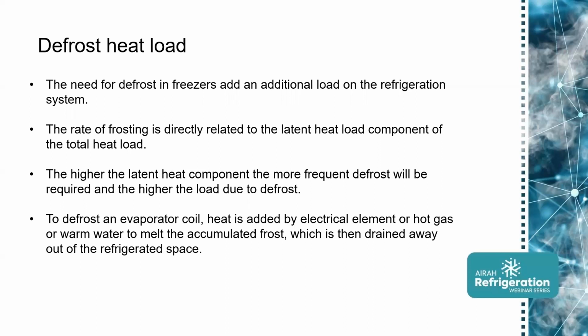The higher the latent component of the total heat load, the more frequent defrosting will be required, and the higher this defrost heat load will be. Because to defrost the evaporator, heat is added by either electric element, hot gas, or warm water to melt the accumulated frozen ice, which is then drained out through the condensate drain out of the refrigerated space.